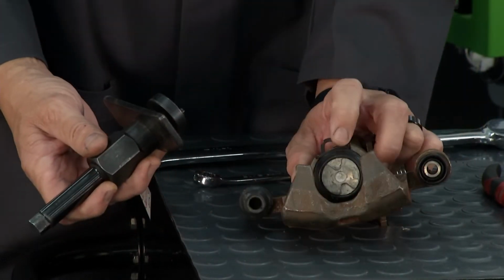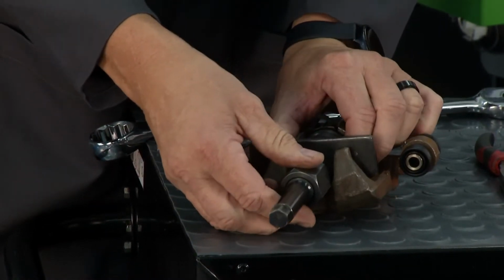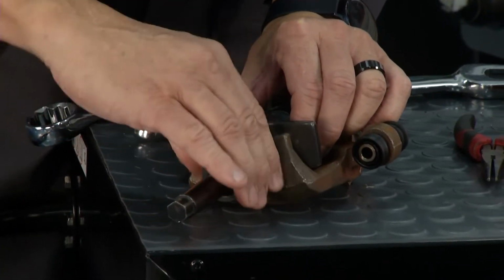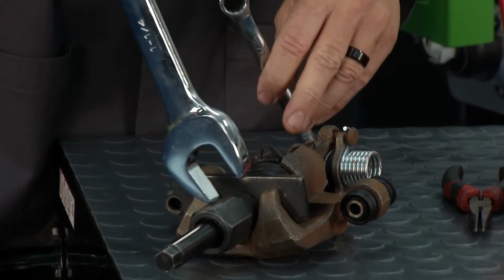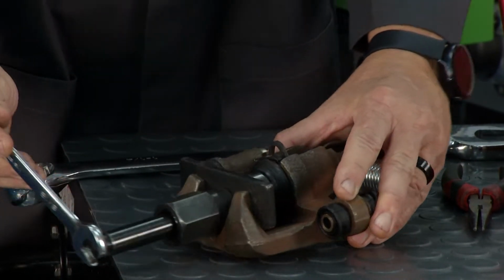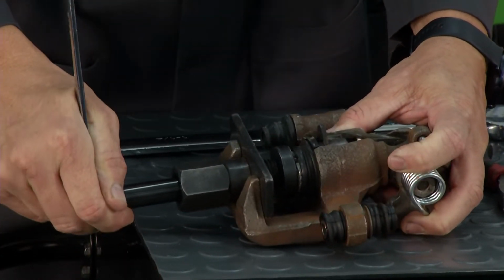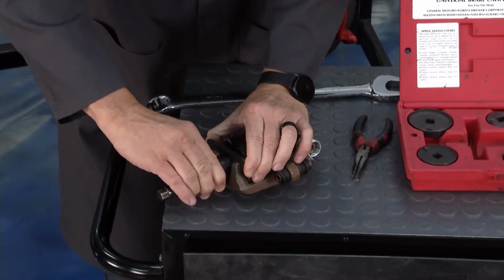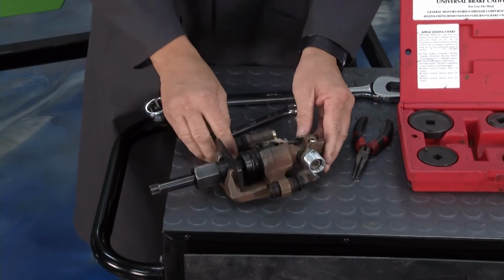So the little dimples right here, I'm going to get the tool and put it in those little dimple holes. What that's going to do is allow me, with the tool, to put a tiny bit of pressure on it. So I would turn this one and put a little pressure on it, and then I'm going to come back and wind it in. When I turn this here, you can see you're actually winding the caliper in just as it would wind out. So that's the tool you have to use when we're dealing with a mechanical driven and hydraulic caliper all built into one.